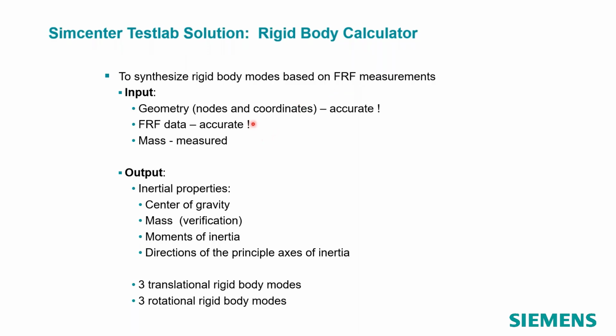Here we want to be a little careful measuring accurate FRFs, because we're going to use a portion of the FRF data you don't normally look at. We're going to be looking at an area called the mass line, between the rigid body modes and the flexible modes. It is going to have very low amplitude. Because of that, it's really important to range every time you rove your accelerometers or your hammer location, because we want that low amplitude to be measured as accurately as possible and moved away from the noise floor.